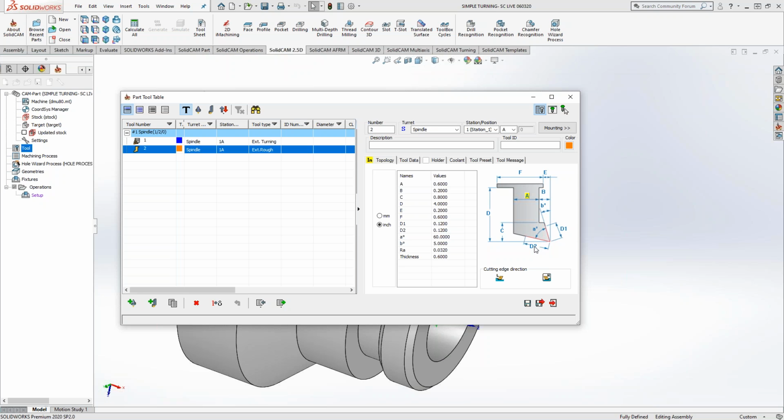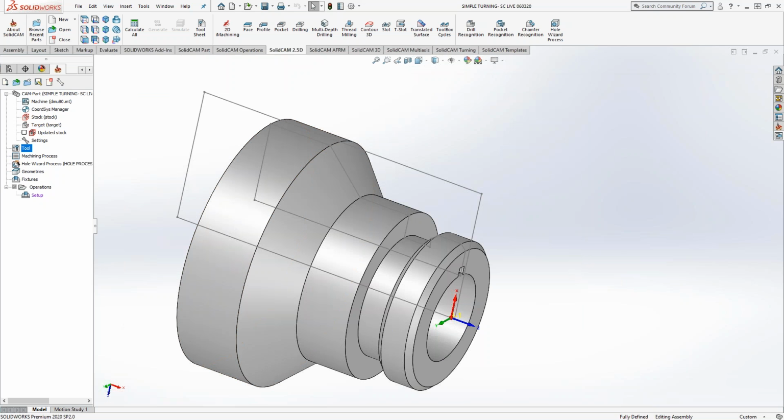This is a little extra work, but this can come in handy if you're using a custom turning tool. Or maybe it's a standard tool, but it has maybe a ground relief angle or some sort of other customization. This could be for whatever you need it to be that is not covered by the composite tools. Oftentimes customers are using the composite tools and they never even touch this section here. But there is always that unique tool that you're eventually going to have to use for grooving or whatnot, and your solid tool definitions will come in handy. Let's do a save and exit.